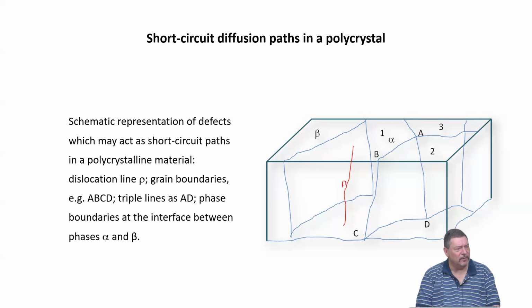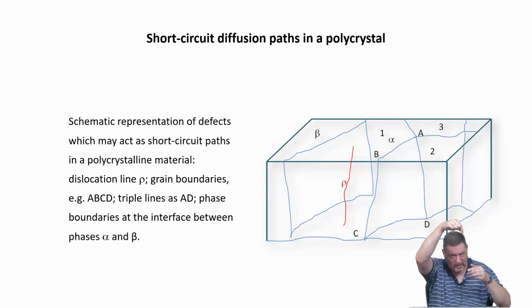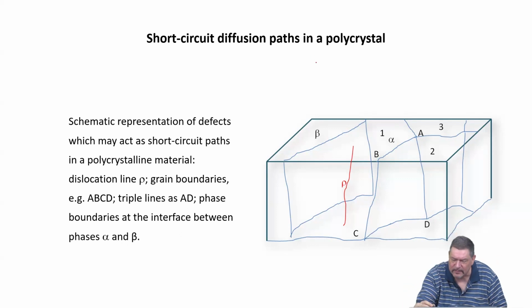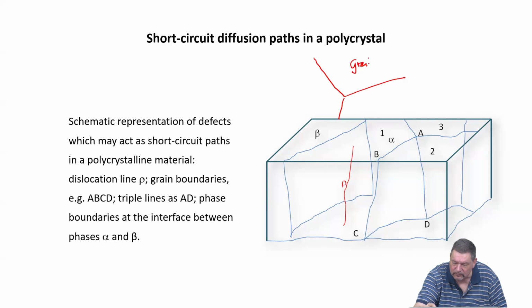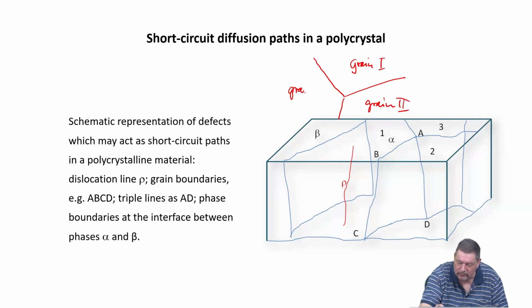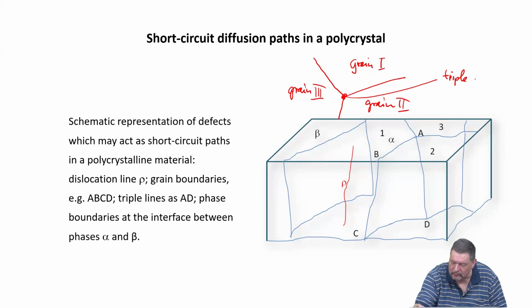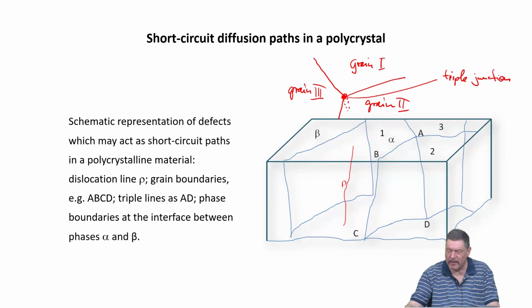Now, after we discussed diffusion basics last week, what would you think would such a triple junction, the line defect that connects 3 grains, so it's, if we look at the cross-section, basically a point, but in reality it would again be a quasi-one-dimensional defect, a pipe.